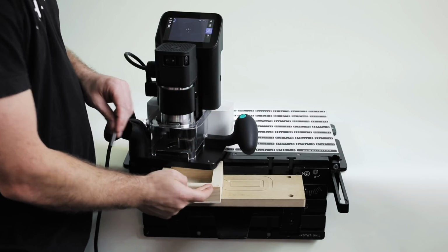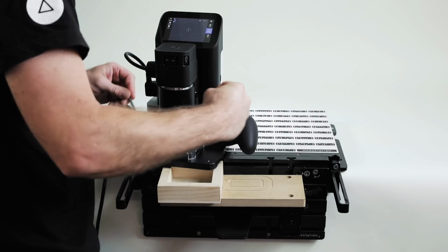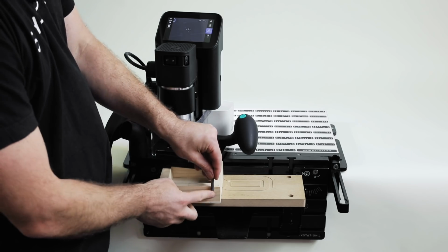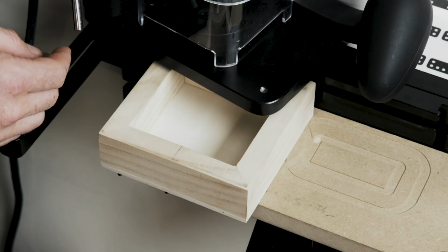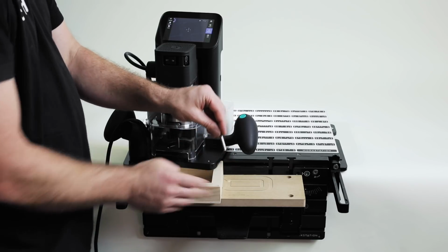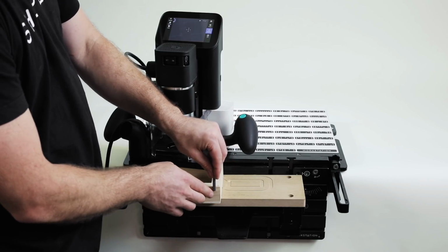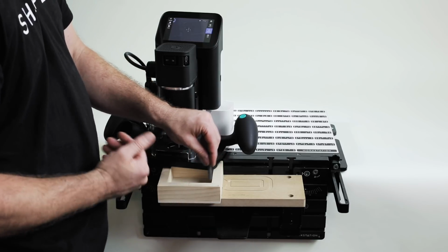We don't want to squash our wood. Pressing too firmly will cause the mechanism to deflect, and it will cause your wood to kind of compress. So that will produce a poor quality grid. It will be slightly offset. So the key is to just come up very lightly, touch the edge. It's a precision measurement, keep that in mind.